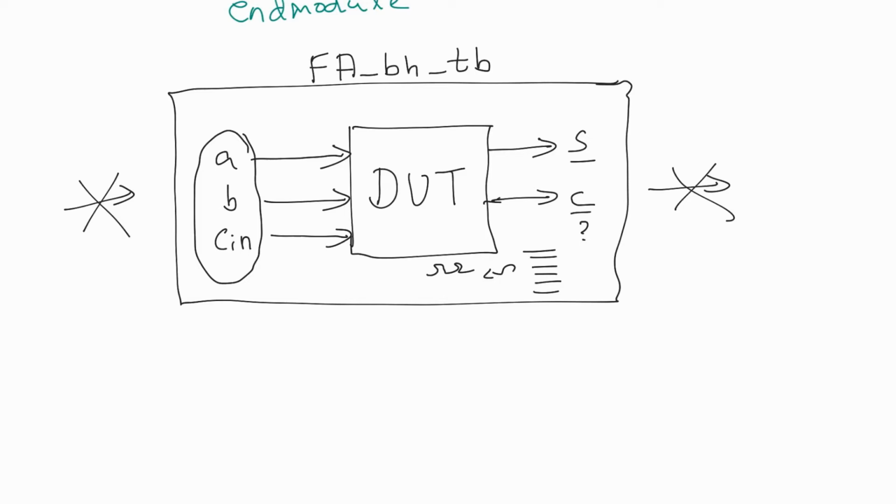So we're going to do these two now for a simple test bench. We're going to display it on a waveform and also print it out on the transcript window. To verify any design, you will need a test bench. The test bench usually has the same name as the module name with an underscore TB. That's the convention, so let's follow that and go ahead and write.